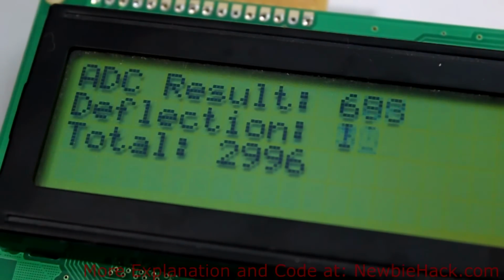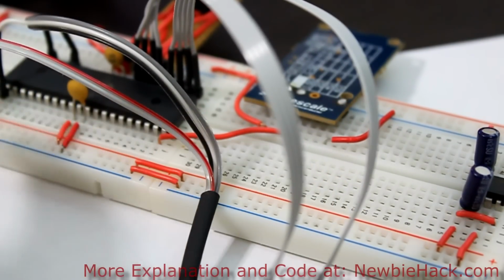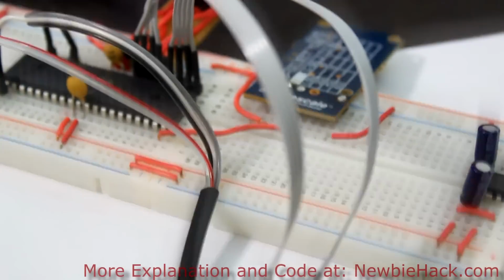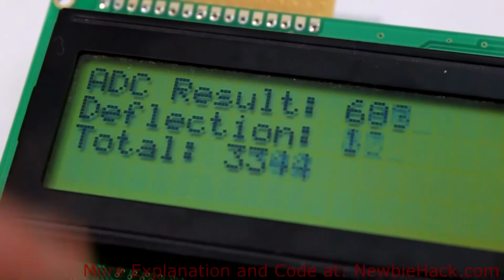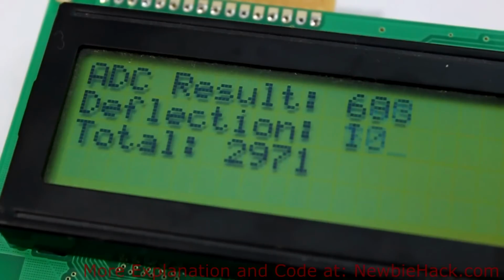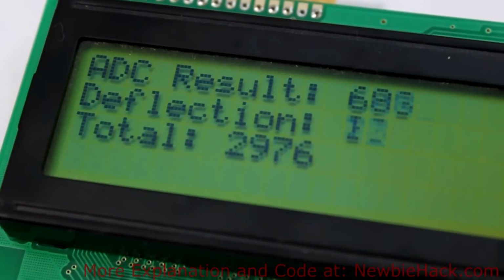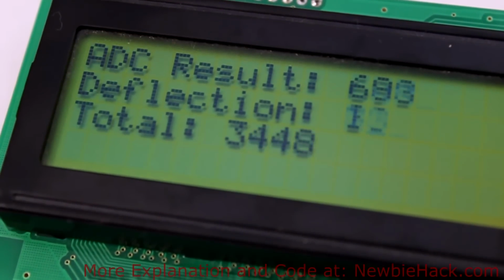Some of the noise could be coming from the actual prototyping environment, the breadboard itself, because there's a lot of metal underneath this, and it can receive a lot of interference. So there could be a lot of noise there as well. So we can see that the numbers are in the 3000s, about 3300, 3500, 3100. So it's probably an average of around 3200. Let's see what happens when we put in a 10 microfarad capacitor.